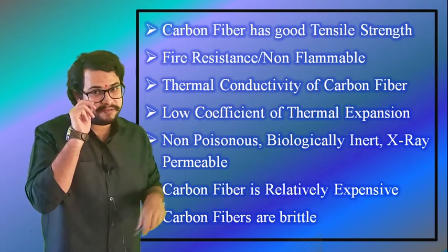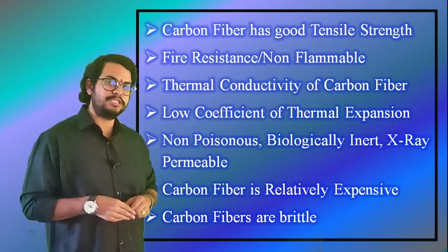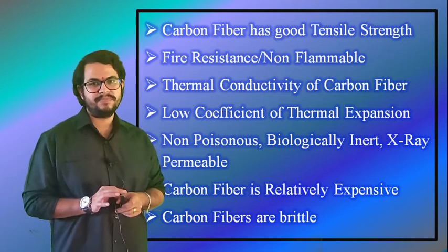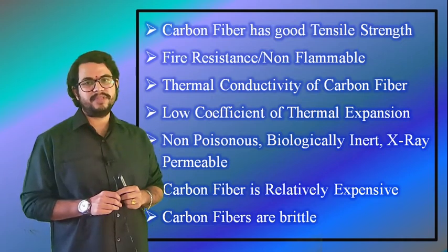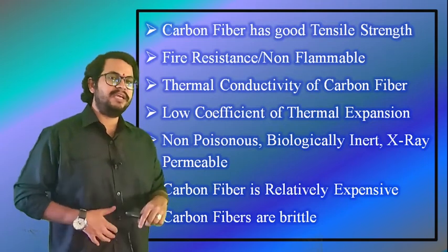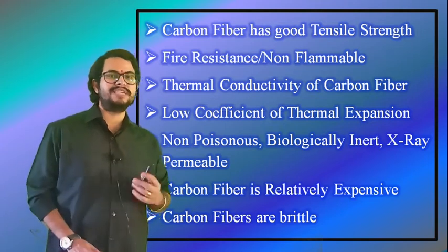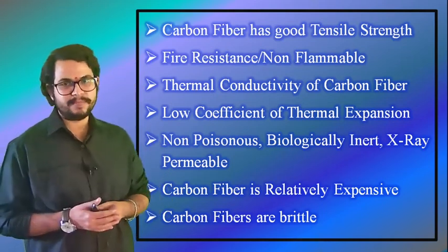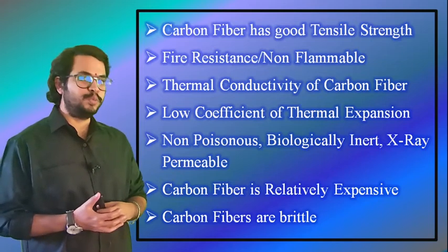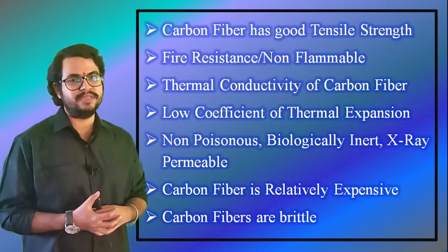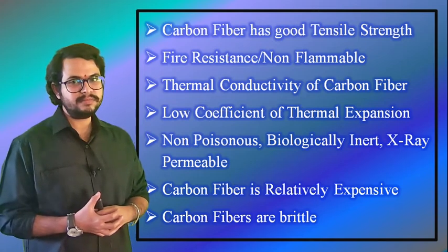Damage in tensile fatigue is seen as a reduction in stiffness with large numbers of stress cycles, unless the temperature is high. The tests have shown that failure is unlikely to be a problem when cyclic stresses coincide with the fiber orientation. Carbon fiber is superior to E-glass in fatigue and static strength as well as stiffness.